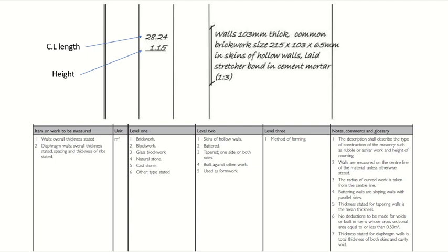Okay, for the walls, we always take the center line length. So if you are calculating the area of the wall, this is an example: you take the center line length of the wall, multiply by the height of the wall. And the height does not include the slab or beam or anything, because it's block, it's a different material. There is no choice here.